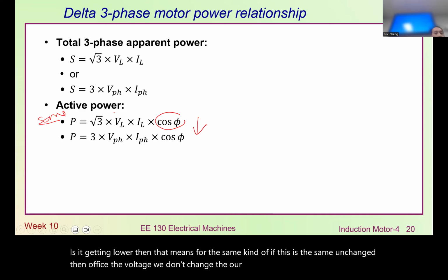So now, let's conduct one simple example, so that from there you're able to understand how to work with them. For instance, we have a three-phase, four-pole motor, 400 volt and 50 Hertz, delta motor. We're now conducting the no-load test and the blocked rotor test. Usually we use these two tests to measure the motor parameters. This is really important. I think for most of the experimental work with an induction motor, we need to understand how to do the measurement.